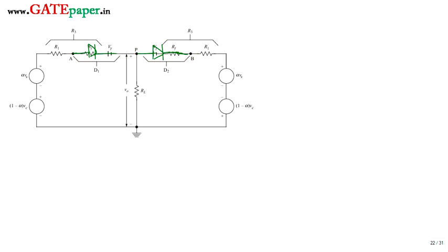So now, if this is the case, how can we go through this? D1 is reverse bias, D2 is reverse bias, so you can draw like this. The equivalent circuit is nothing but here you are going with R1, and the diode is replaced with an open circuit, diode 1, and later it is going with RL, and diode 2 is acting as an open circuit. There is no forward resistance RF since it is reverse bias, so we are only considering R1 only.